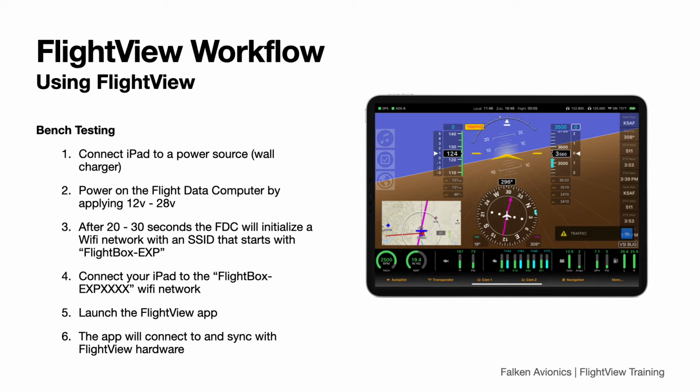Before we dig into all the screens, it's worth taking a second to talk about the workflow you'll use with FlightView. Most users set up their system on the bench first before they install it in their aircraft, so we'll first do a word about that. To start out with, FlightView uses quite a bit of power since it stays in the foreground at all times, with several radios running and with the backlight cranked up. While you can run it on battery, if you're going to be using it for more than 30 to 45 minutes, we recommend you have an iPad plugged into a charger.